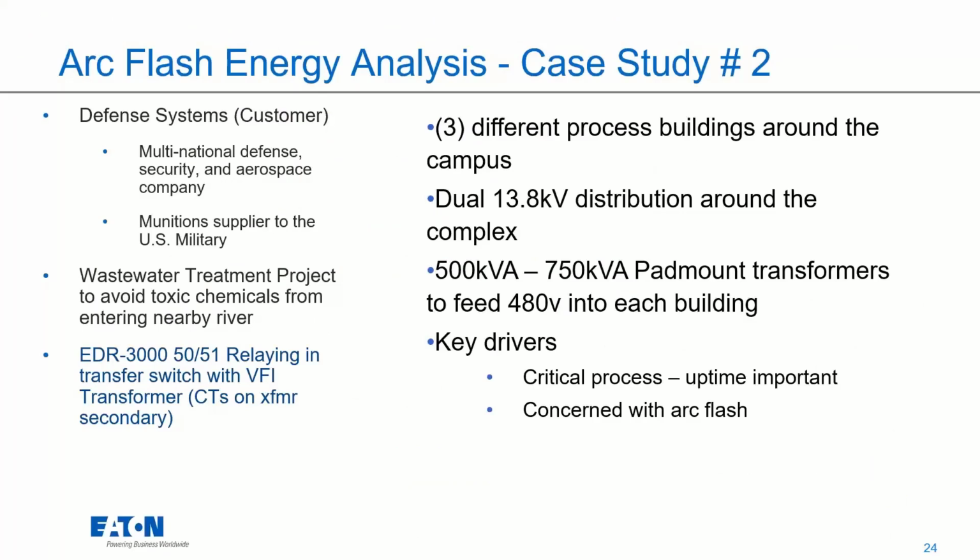Okay, so we can go ahead and look at a second case study, and this one is for a wastewater treatment plant that's powering pumps to avoid chemicals from getting into a nearby river. So this is very important from an uptime perspective, where it needs to be in that always-on solution that we were talking about. And in this case, the customer did require less than 8 calories per centimeter squared.